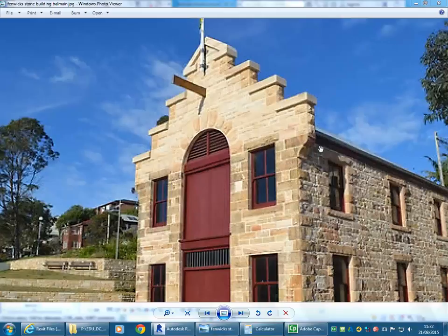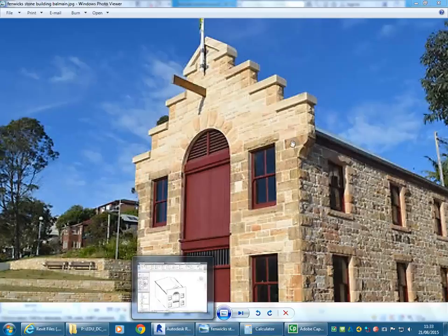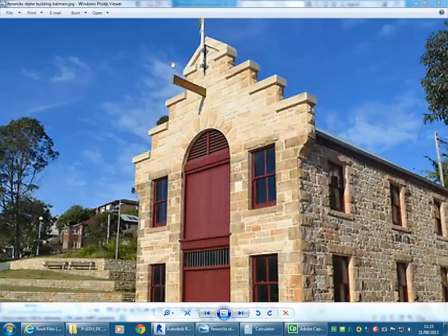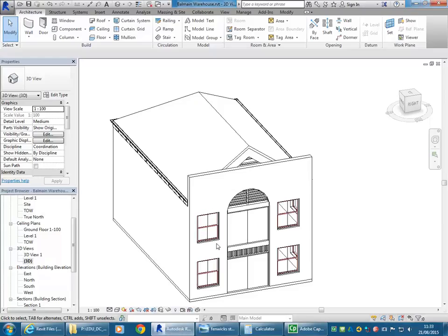Okay, so now that we've got the roof and the fascia and the gutter modelled in, along with the wall at the front set to go all the way across the front of the building, ready for the parapet. Now we can finally do the stepped parapet here to cover that roof gable form at the front.